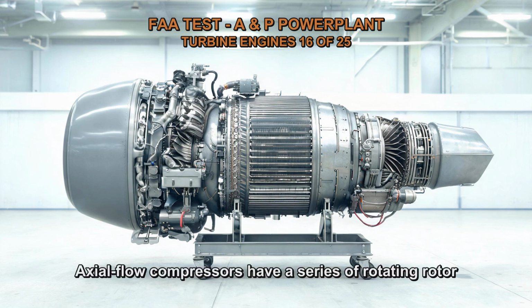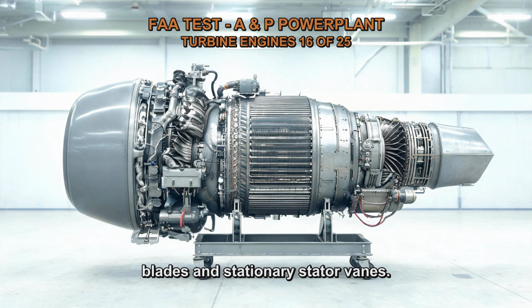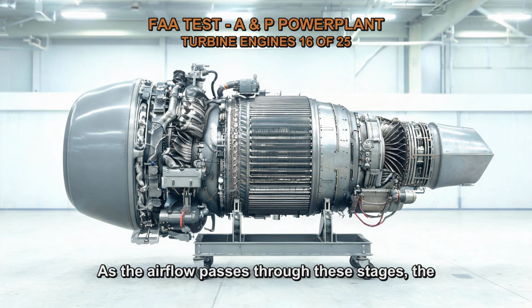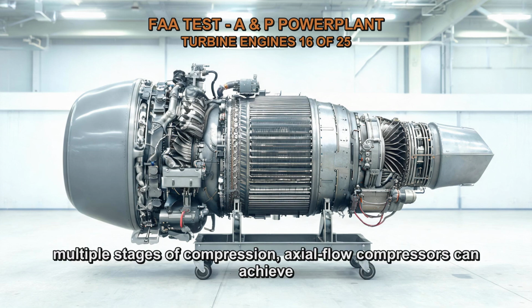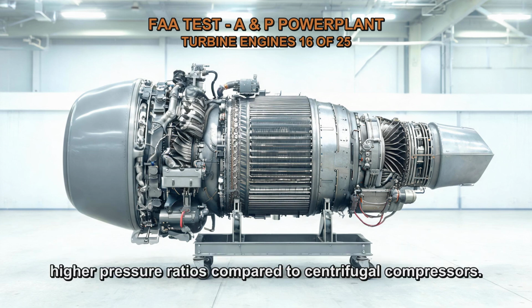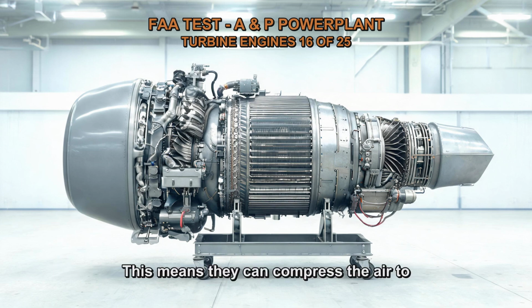Axial-flow compressors have a series of rotating rotor blades and stationary stator vanes. As the airflow passes through these stages, the rotor blades accelerate the airflow, and the stator vanes help to guide and redirect the airflow while increasing its pressure. Due to the axial flow design and the multiple stages of compression, axial-flow compressors can achieve higher pressure ratios compared to centrifugal compressors. This means they can compress the air to a higher pressure level, which is crucial for efficient engine operation and performance.